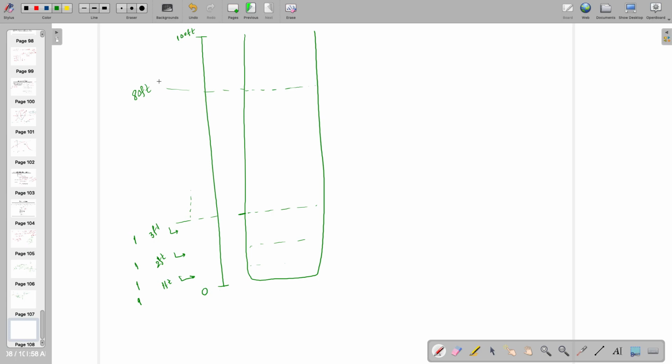Every time you will see that if it is till here, all 1 here and others are 0. You will never see a code where some of them are 0 and then 1 1 and then 0 0. It's not possible in such a condition. Such a code looks like a thermometer, so this is known as thermometric code.